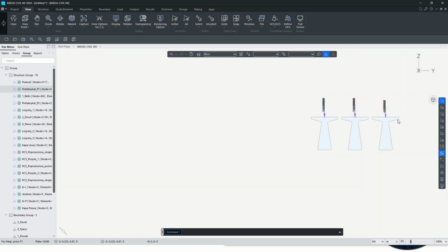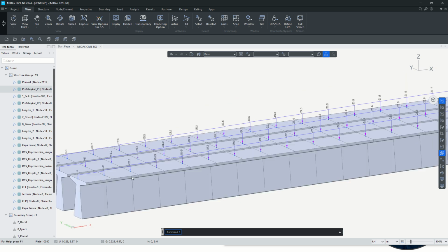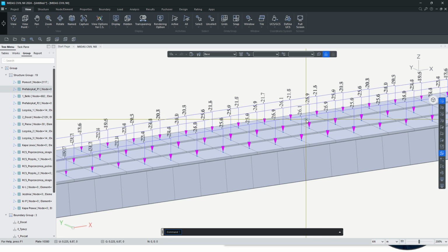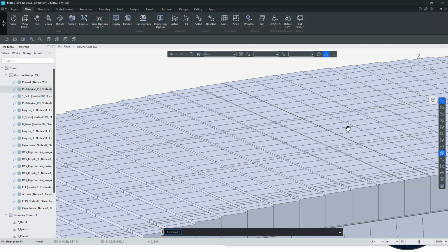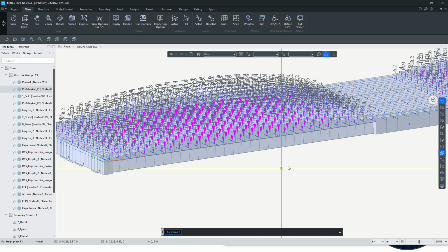a couple of beams, these have different spacings, so the amount of wet concrete at the middle of the bridge then is different between them. Here you can see about 26.1 at the largest amount, here 21.7, and this is just from different spacing, so each beam has its own load and it's taken into account. Here all the construction stages are added, everything is here added within the program, and everything works.